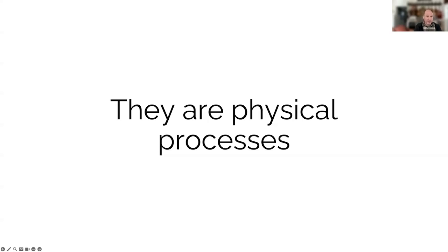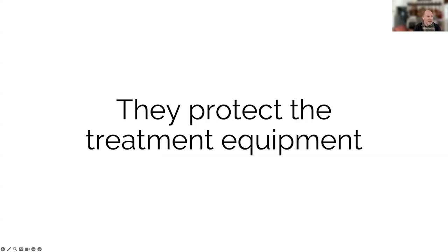All of the kinds of debris that you are trying to remove in preliminary treatment can damage pumps, they can clog pipes, they can take up space in your process tanks further down the line and really negatively affect their ability to do their job correctly. And that sentence I just gave you gives us the real reason that we have preliminary treatment processes in place. They protect the equipment that's further down the line.